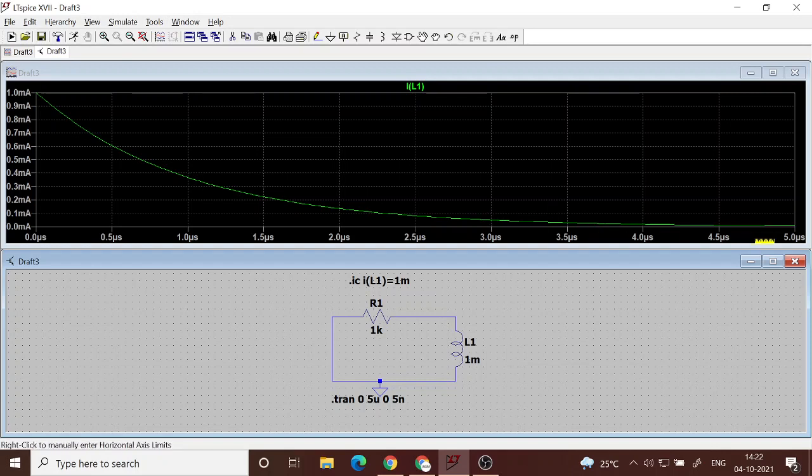If you plot it to say 50 microsecond, then we won't be able to see the details. Okay, we will only see a sudden discharge, and then it goes to 0, and then everywhere it is 0. And on the other hand, if I reduce it to say 1 microsecond, then I will only see a portion of this wave. So it is advisable to plot things to an extent of 5 time constants.